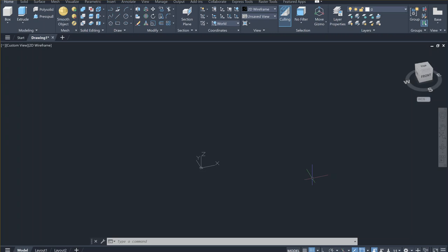you have to use 3D polyline. 3D polyline or spline will work. But if you're using the line command, you're only operating on the XY plane. How do you draw a line in the 3D world? Well, you rotate the UCS so that the XY plane is perpendicular to your view. But in time, you will see applications of everything I am saying. It may not make sense at the moment, as much as it makes sense to me right now.